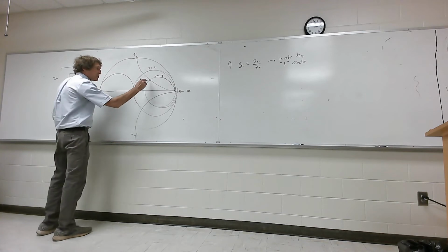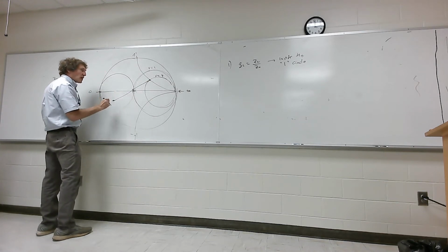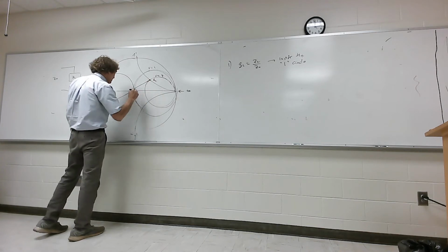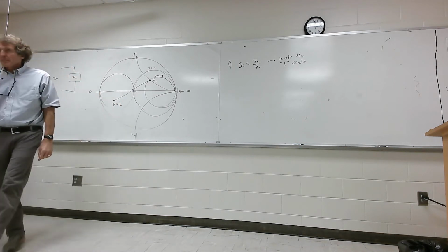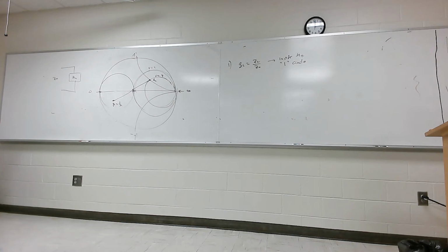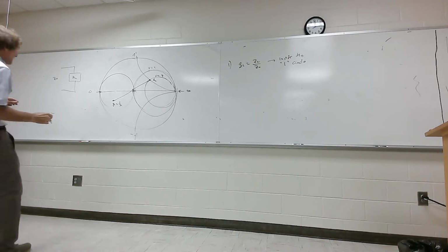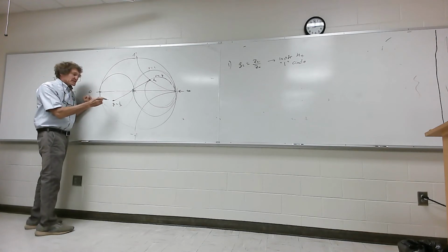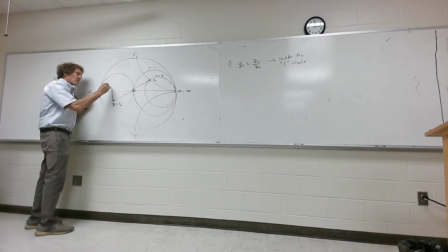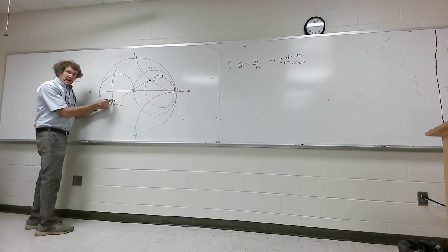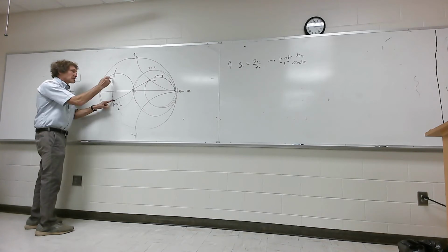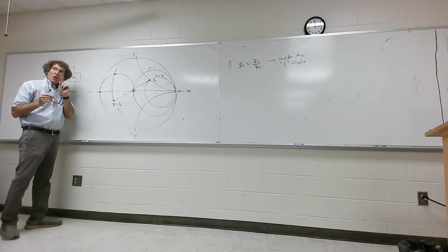So we go to the opposite point. We go to the conjugate point, which would be Y. So if this is my ZL normalized, this would be YL, which is 1 over ZL. Y'all follow me on this? Alright. If we're inside the one circle, we're going to the admittance domain. Now, admittances you add parallel. Y'all follow me, class? Alright, so if I'm over here, now, just pay attention. You remember these trajectories for the real part are going to look like this, right? That's the admittance. I can add minus jB something and get to this point, or I can add plus jB something and get to that point. Y'all follow me? Now, why is that important?